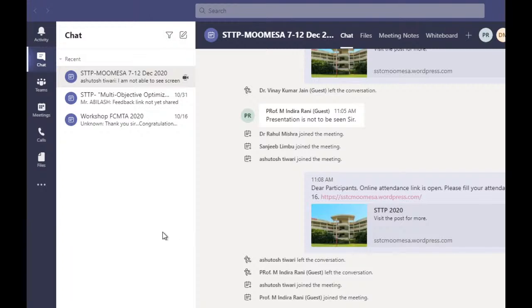Since we are going to learn only one thing, which comes under Stat, under DOE, that is design of experiment, and you might have already covered factorial, today we will be seeing response surface methodology. You can see it is under Stat, then DOE, then Response Surface. Here you can see Create Response Surface Design.